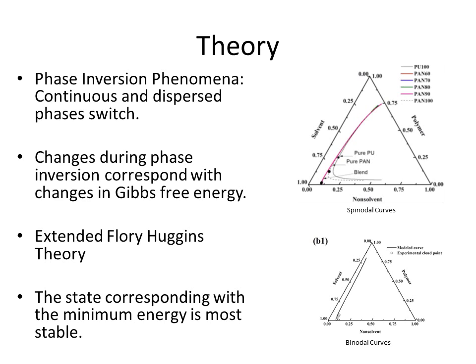If you have just a little bit of water, you have water droplets dispersed in oil. And if you keep adding water, eventually you'll have a phase change where you have oil droplets dispersed in water instead. Per the authors, the kinetic study of phase inversion phenomena requires the knowledge of a complete phase diagram to identify the phase inversion mechanism as spinodal demixing or nucleation and growth phenomena. This mechanism of phase inversion in turn explains the formation of asymmetric structure in the case of spinodal demixing and symmetric structure in case of nucleation and growth.